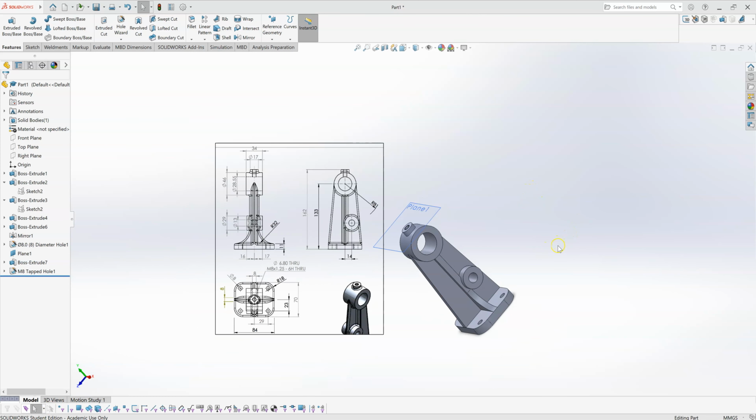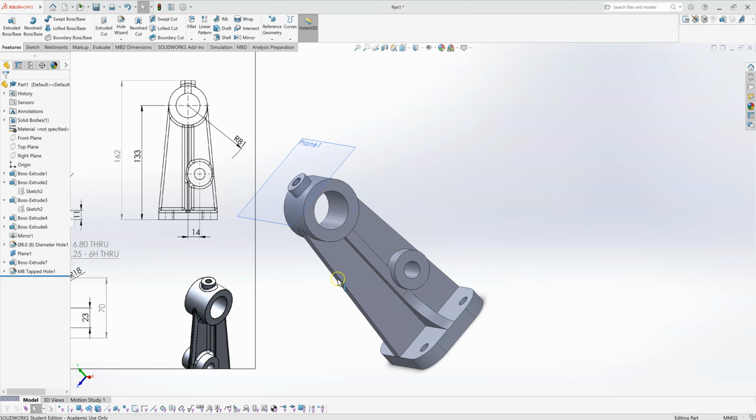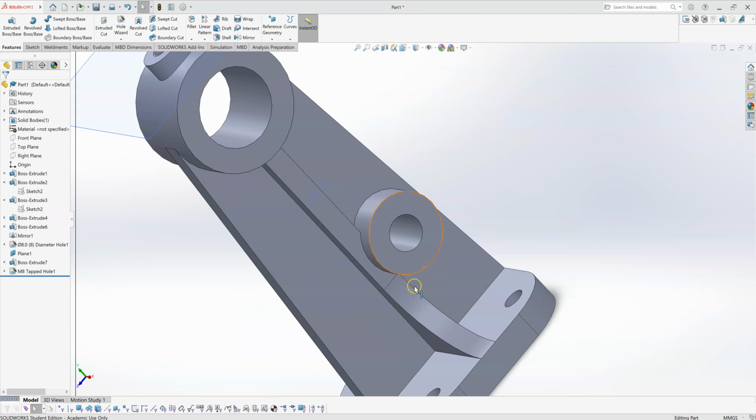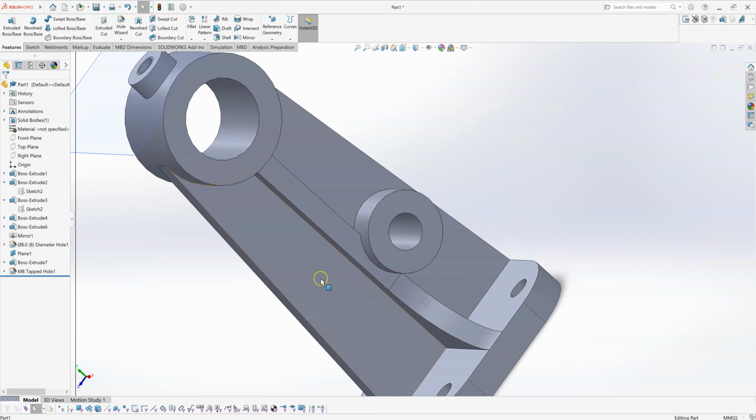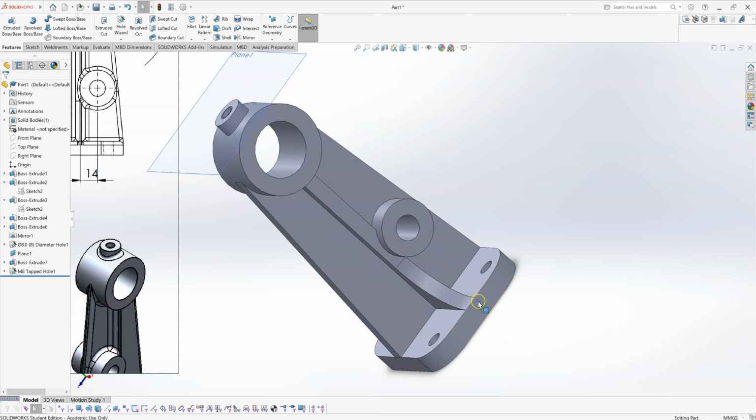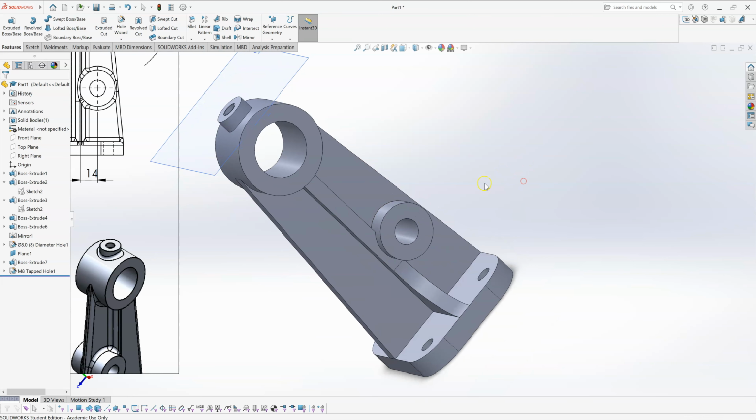Now I think I might actually just carry on and finish it out with the fillets at the end. So as I said, there are quite a lot of corners and features in here and intersections between different features that need filleting. If you try to just throw everything into the one fillet command, you can get errors with the intersection of different fillets. So I'll fillet this in a couple of different passes.